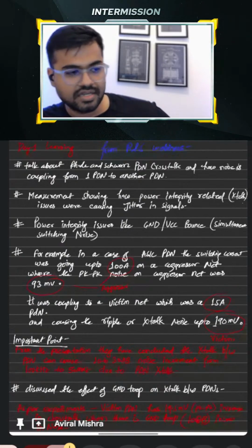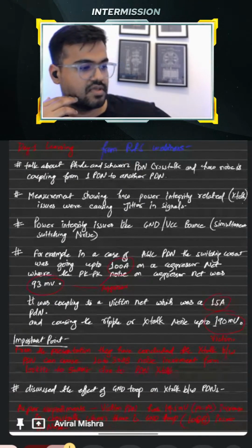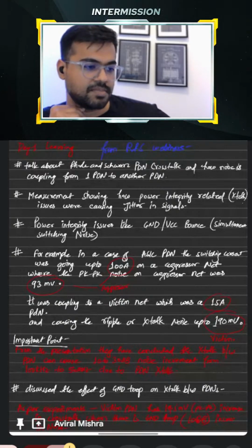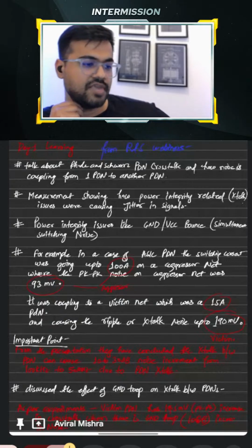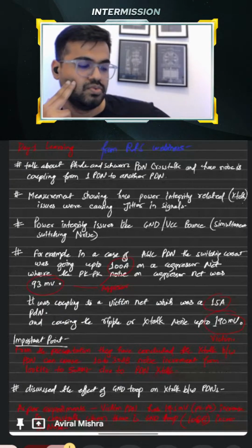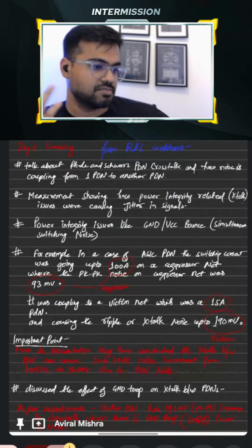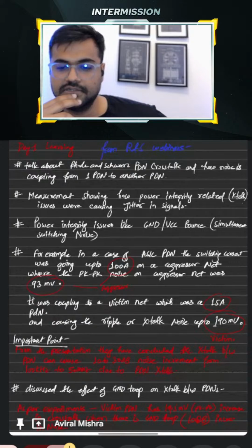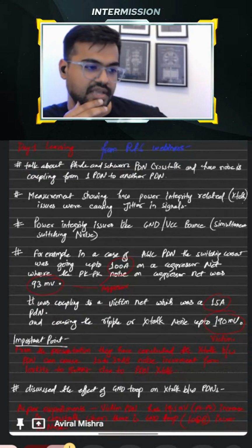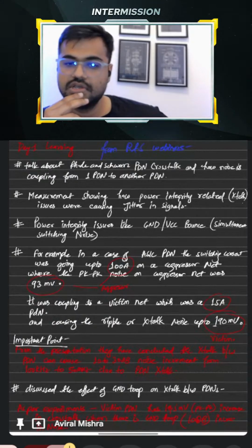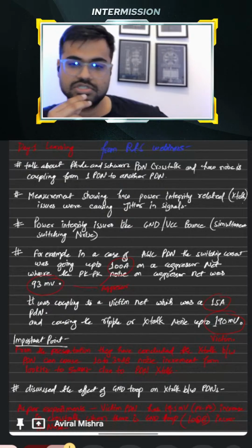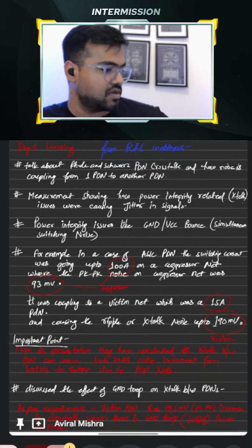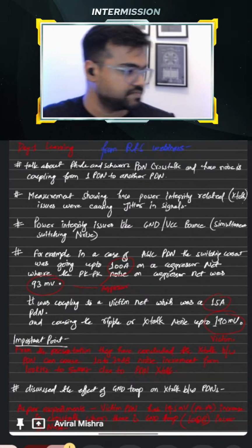Here net means power delivery networks. So let's say we have two power plane sections in a printed circuit board, and there is some electromagnetic coupling happening due to the switching on those power delivery networks. That we call PDN crosstalk.